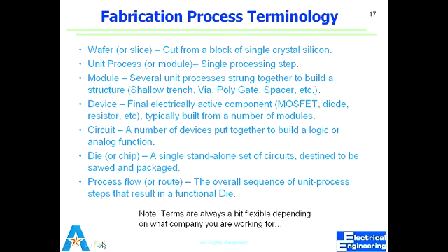When I say via, you would be readily clear what steps may go into making a via. We'll do this practice over and over with many things. Polygate again is using a polycrystalline material to act as an electrode. Heavily doped polysilicon is used almost like a metal, so we use it for gating. Spacer, again, is putting some object. So many things which we'll see are composed of a number of steps that go into them.